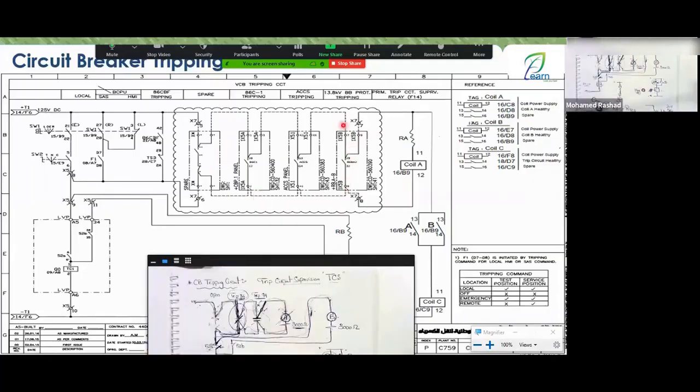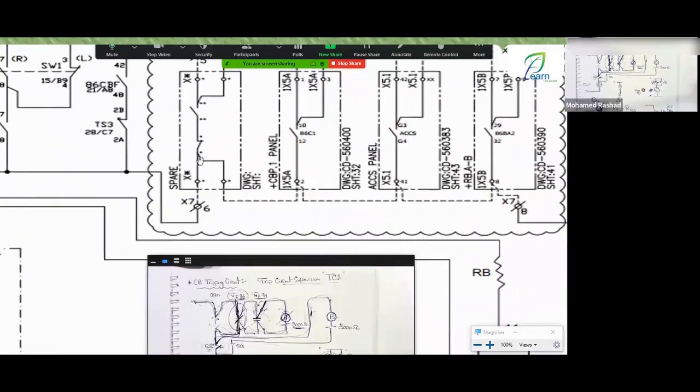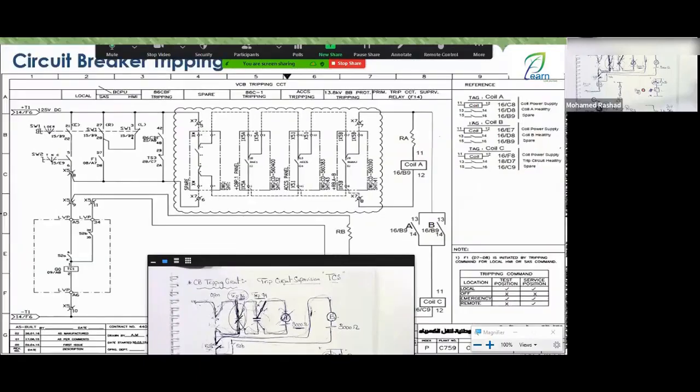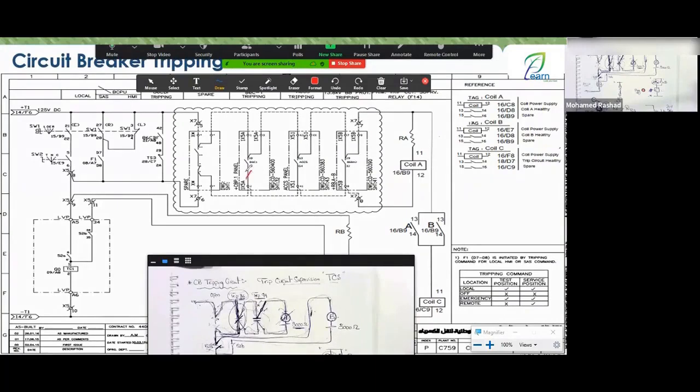Okay, you might agree with it or not, but I'm telling you, from my perspective, I'm saying this is wrong. It should be like this above here, with a terminal block here and a terminal block here, all right? And it should look like this circuit here. Look, see here, it took us to a block, went to the contact and came back. It was supposed to do the same action here and the same action here and the same action here. Engineer Rashad, because quite simply, if I came here and told you this wire is cut, did you see it? No. Why? Because here the positive is moving normally in your circuit. It went to coil A and came back from coil A like this, returned like this, and continued normally, completing your circuit. It's not even looking at this wiring, right? Am I wrong? So if this is cut, or this is cut, or this is cut, you have a problem.